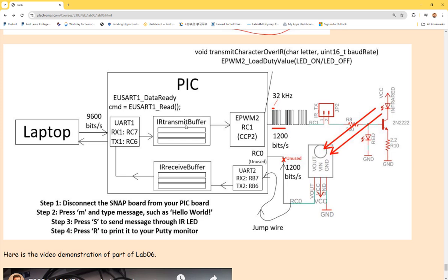So you have to program your PIC to receive byte by byte and save it in an array, so you are not losing anything. How do you decide how big to make your array? Just don't make it too big. I think 32 is the maximum, depending on the system. You don't want to make a super long paper, but it won't be able to handle that. So there's a limit on the memory. So it's already saved in there. You don't have to worry about losing any of the data.